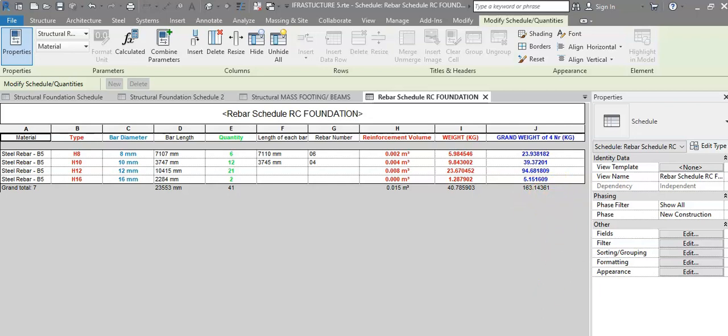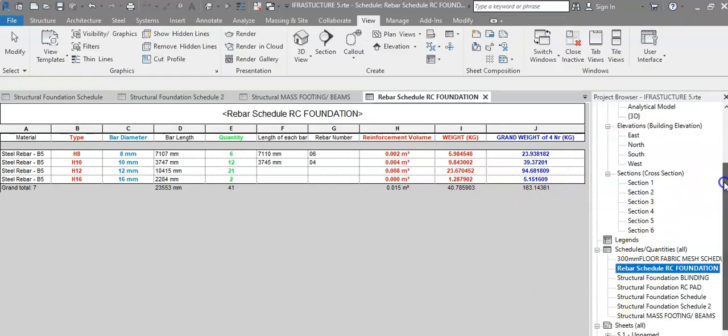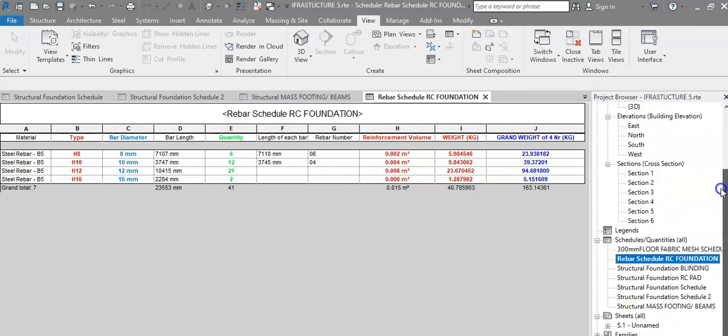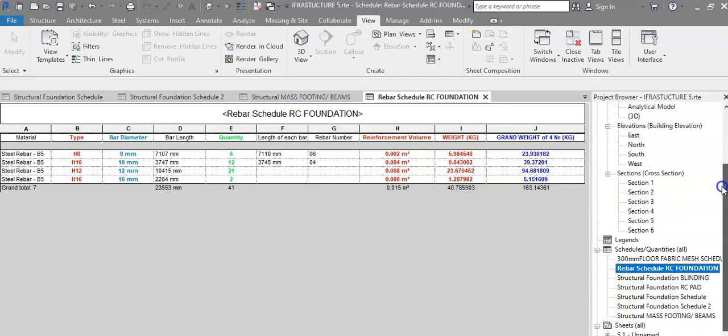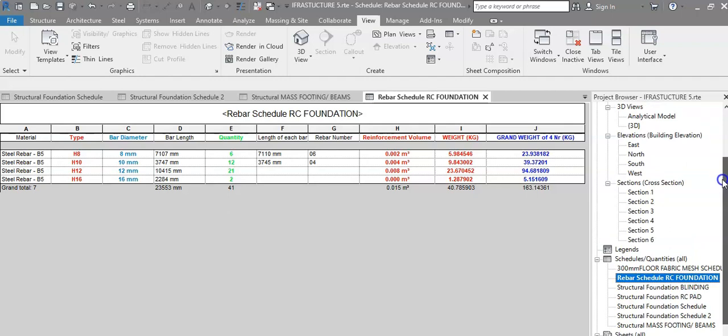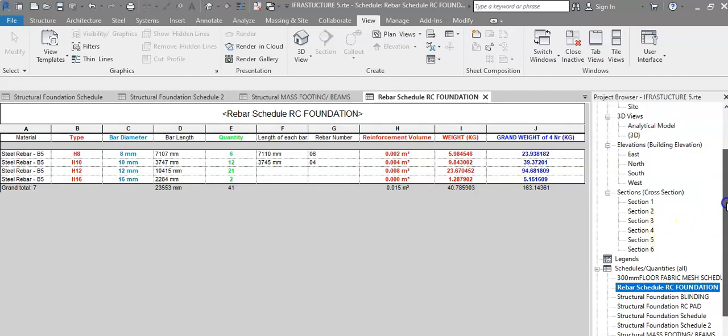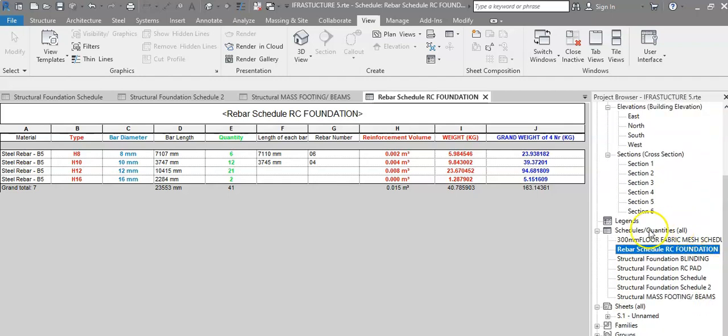So now we looked into how we work out the volumes for earthworks, including the topsoil. And as I said, hopefully in the next tutorial we can look into how we work out the volume for down to formation, foundations, and other items. And we looked into how to work out the volumes for concrete, for rebar, fabric mesh, and all these items, which can be worked out instantly and digitally with modeling the project.